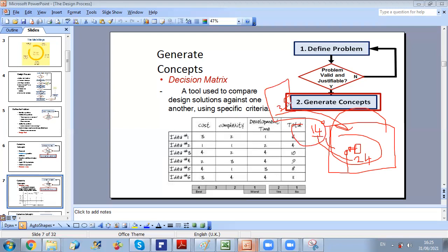So to be able to reduce this percentage of fresh air introduced, we can assist this system with personalized ventilation, which will provide the occupant directly with fresh air. And therefore, I need a lower amount. And also, I can ensure localized comfort. So I can maintain a higher temperature in the space, while in the microenvironment of the occupant, I have an acceptable level of comfort. So this is a very good strategy. It will save energy, it will ensure comfort, and it will enhance the air quality.